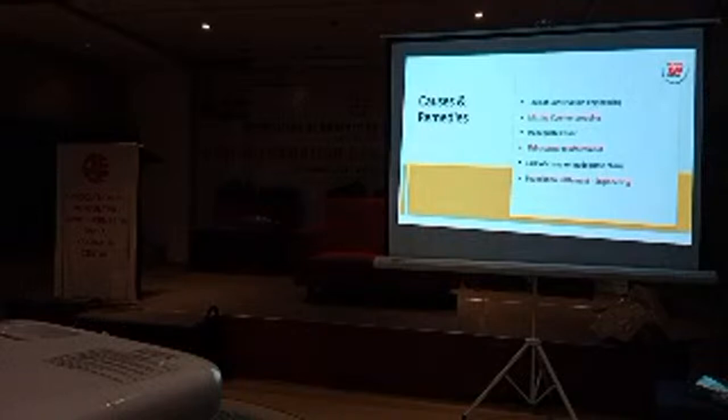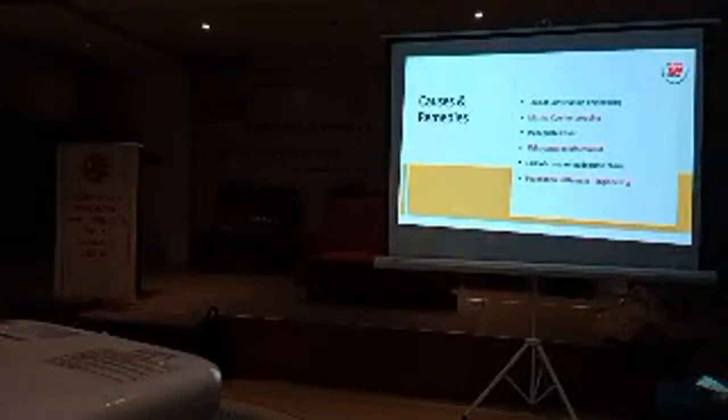Inadequate cover, slab reinforcement, inadequate chairs. This is also very important. We have to specify in the drawing what is the diameter of the chair, spacing of the chair, and what is the maximum length you can go for in the chair.